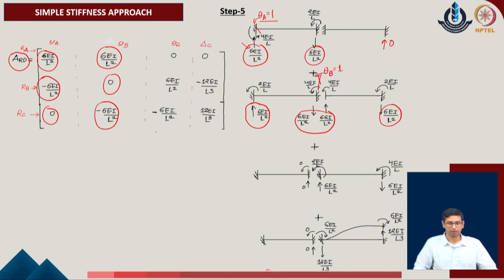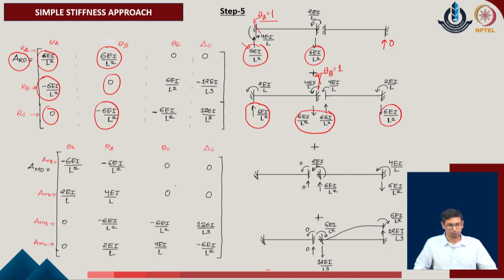In the similar manner, one can also evaluate the response of the system with respect to the internal member forces. As we are applying the unit deformations in the given problem, we are also generating these support reactions, and with respect to those, the internal member forces can also be identified.